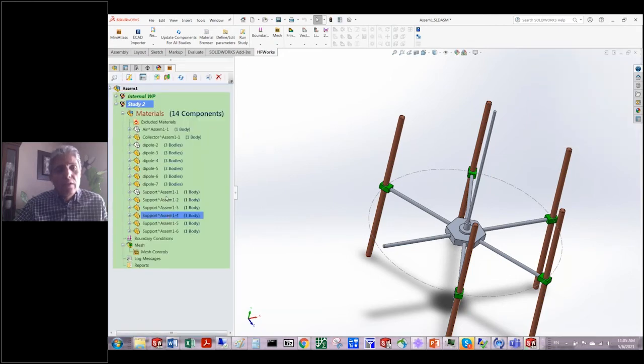You can see here, it's showing me all the parts that I have in the model, and these are labeled materials. So it's telling you that we need to define these materials. Then we need to define some boundary conditions and excitations, and we need to have a mesh. Those are really the three very simple, very basic steps. And you've seen in the study definition that this is SolidWorks compliant. So you're using the same process. It's as if you're executing a SolidWorks command. So you would apply materials, you would do boundary conditions, you would generate a mesh, and then you would solve the problem. Okay. I don't believe I have enough time to walk you through these steps.